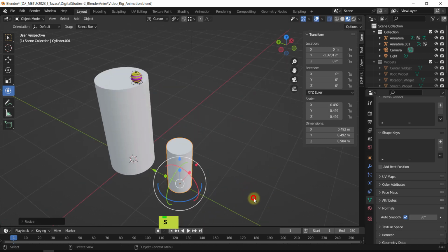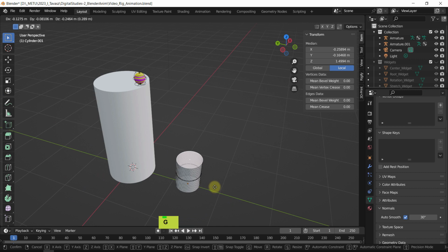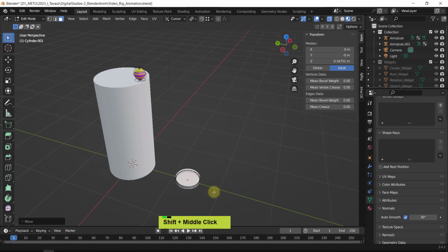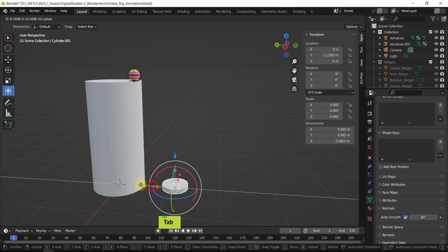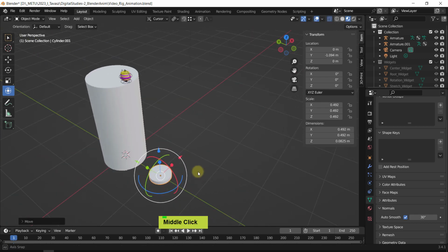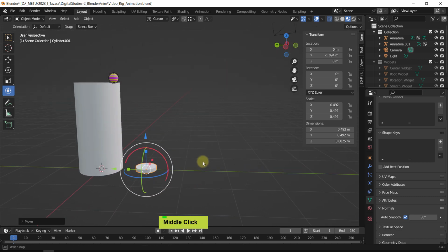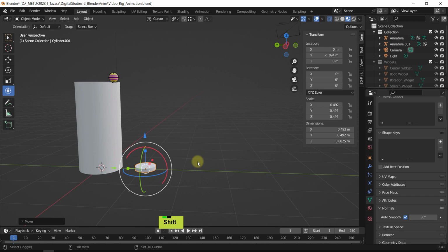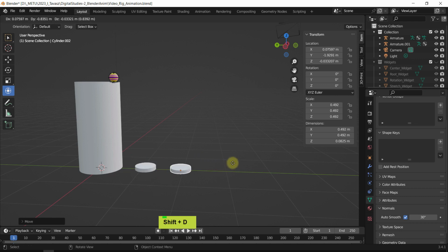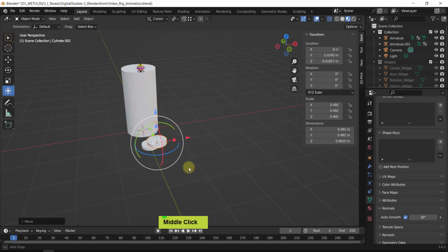So let me scale this down. Go into edit mode, select the top polygon, and just use G and on the y-axis and scale it down. So that's kind of a platform where the ball will jump on. Okay, so let me leave edit mode, move this in here, and that's where we start. Now the other thing, when it jumps on, just design a kind of little bit of an environment for the ball. So it will jump in here, and then maybe Shift D and on the y-axis, and G on the z-axis, going up, and maybe a little bit offset.